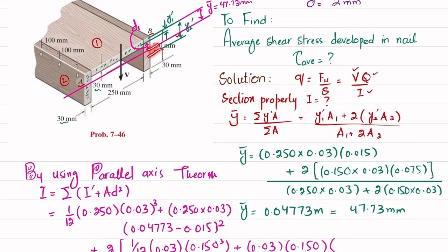So this is the mid of second section and this is the neutral axis. So this distance is d2, and this can be obtained if you subtract y dash from this y2. You can see that if you subtract this distance from this distance, clear? So you will be left with this.